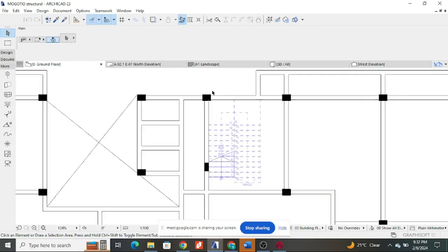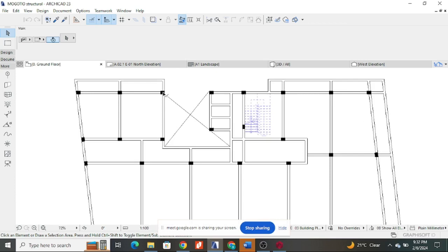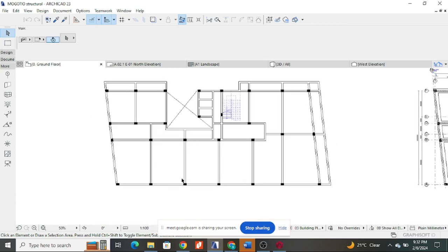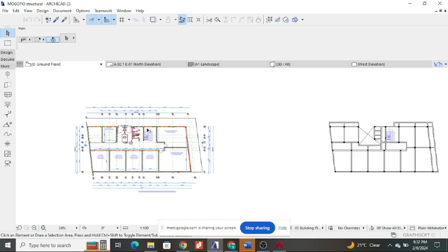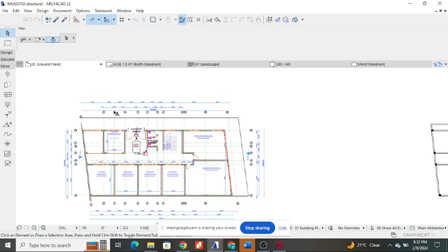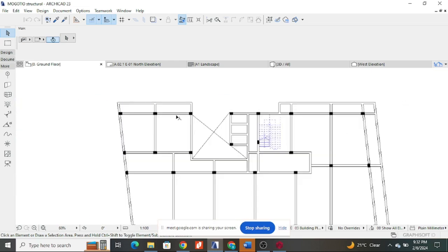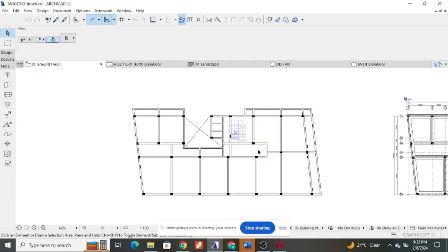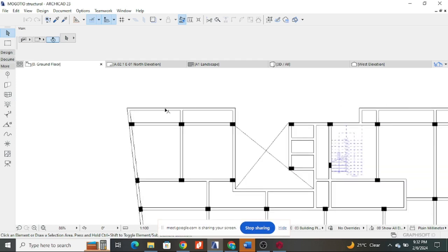And after I generated the beams, I decided to position my columns now. I was guided by the ground floor, but after I have drawn the ground floor, you realize the ground floor cannot show me the balconies that exist. That is when I took my drawing to the first floor and found out which disparities exist in my drawing. I realized I had a balcony here, so I had to extend this to make the balcony. And I had to make these beams behave as cantilevers.